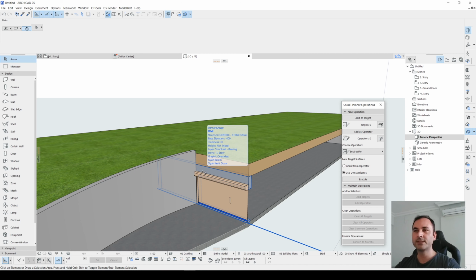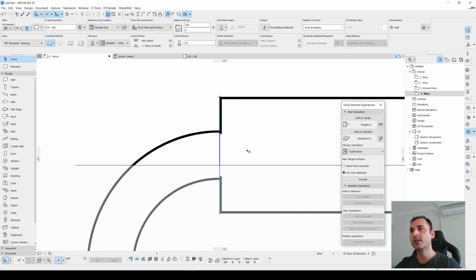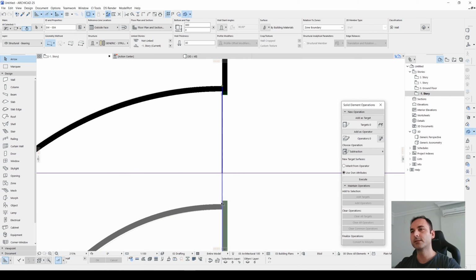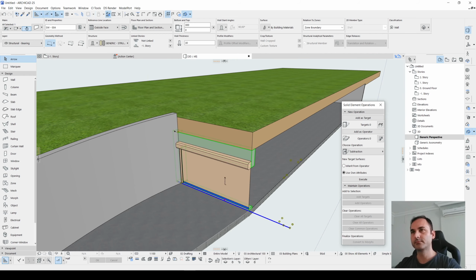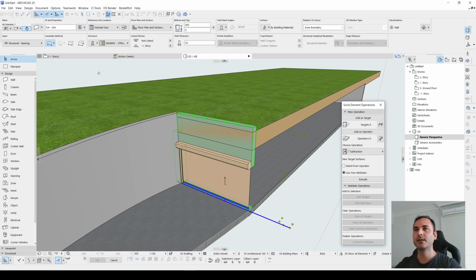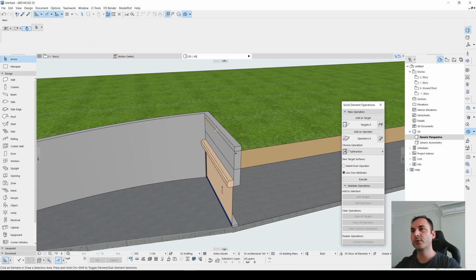Of course, we have some things to do here. You can create an additional wall up to there, or you can split it apart. I'm going to split this for this tutorial. Let's split it from here to here and here. Let's click the top point and stretch height and match. Of course, we need to cut some additional parts from here.